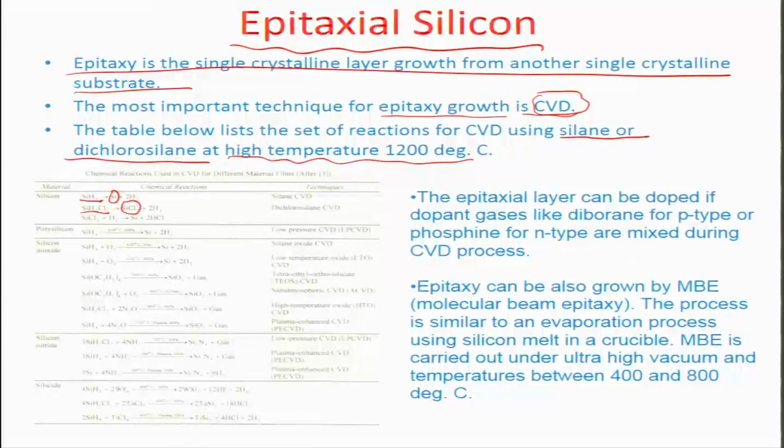And then again the hydrogen, which is in excess in the chamber because of stoichiometric reasons, again reacts with SiCl2 and formulates the silicon and an acid residue. So, with the chlorosilane chemistry or with the normal silane chemistry using a cracking temperature of about 1200 degrees Celsius, one can generate solid films, thin films of silicon, and they are also crystalline in nature.